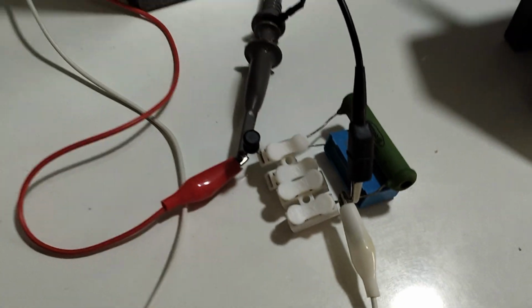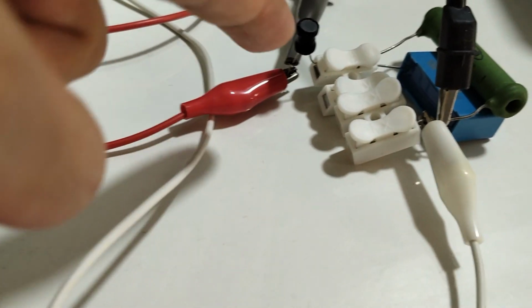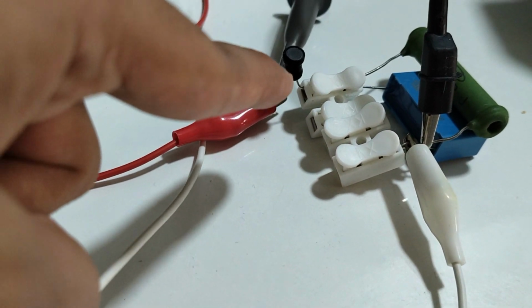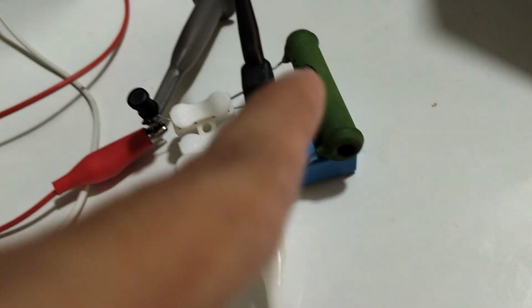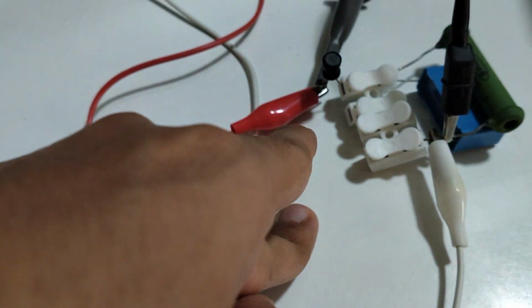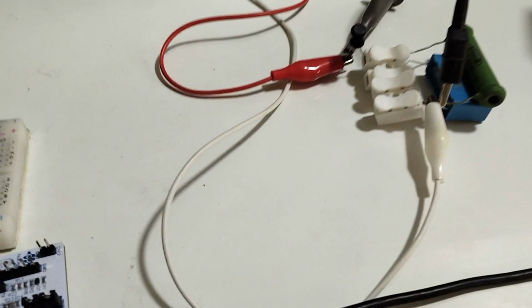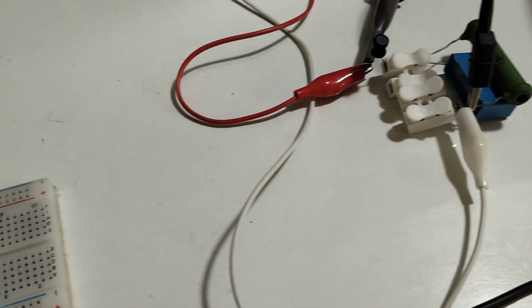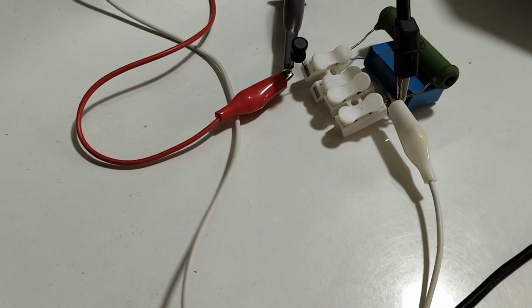Currently it might look a bit messy since I have my oscilloscope plugged into it, but this is the LC filter. As I said, we need to filter the output, right? So the LC filter consists of an inductor here, a drum type one, this black one, and this blue capacitor, which is across the load, our 100 ohm resistive load. The inductor is 1 millihenry, and the capacitor is 1 microfarad. That roughly gives you a cutoff frequency of around 5 kilohertz. And since we're doing 25 kilohertz switching, the cutoff is decently below it.